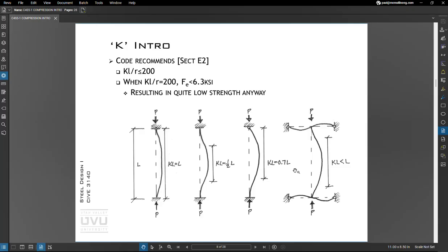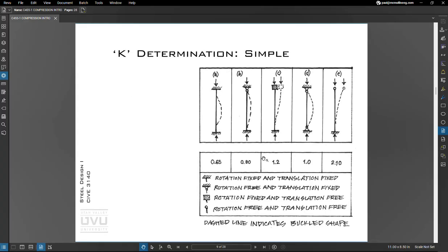Another thing we need to look at carefully is what the boundary conditions of our columns are doing. A lot of times in column design, we may have different end conditions that will affect the buckling length. In some of these examples, you can see a fixed end, and the effective length is basically half the original length. Kind of condensing that into a simple chart.